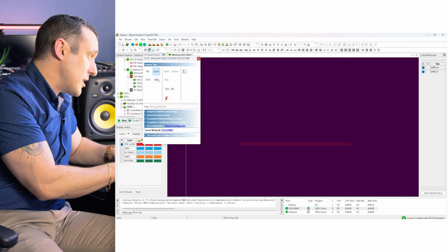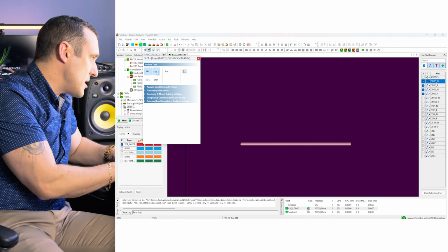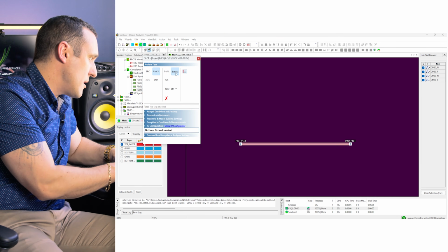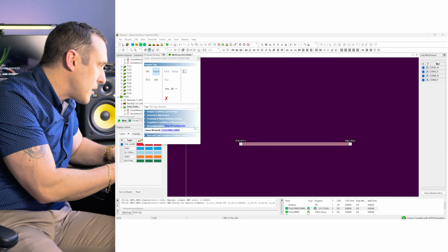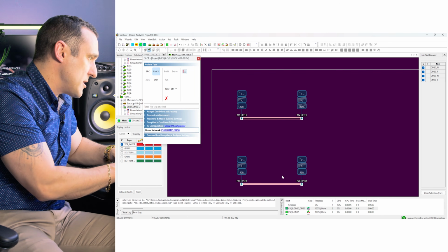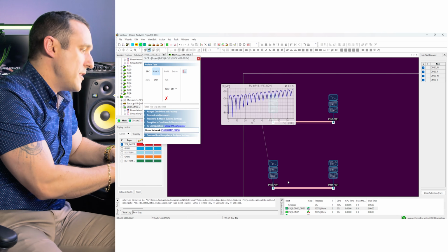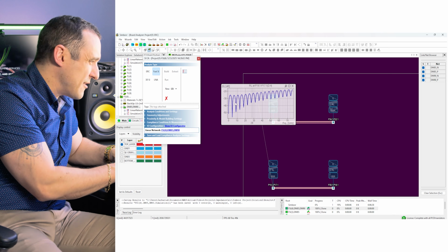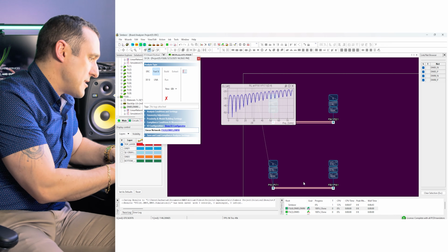So pretty good. If we go back here over to ERC, select this one, hit build and extract. I just click through the wizard again. It's going to go through and collect all these measurements, and we can do a quick comparison here. You see also these microstrips are at about negative 30, negative 25 dB up to about 20 gigahertz, and then they rise a little bit higher.